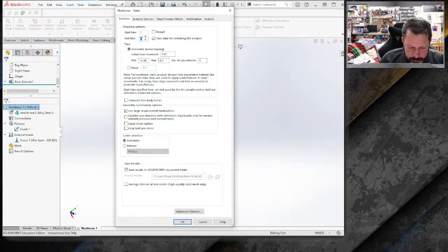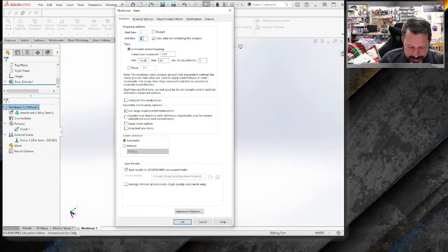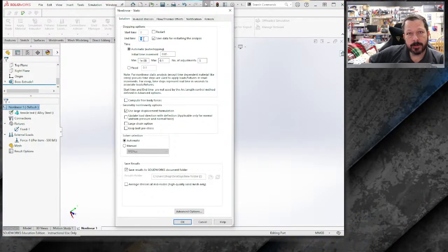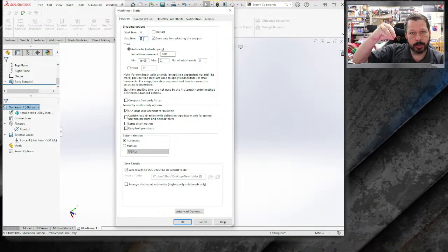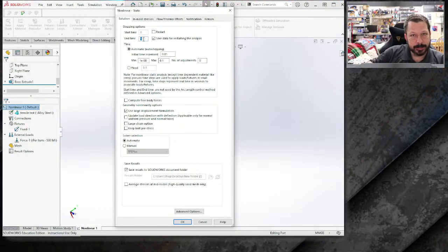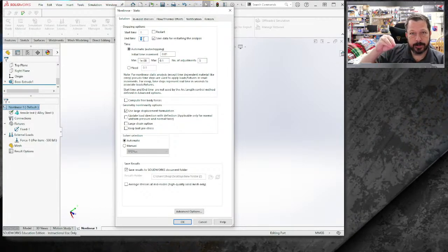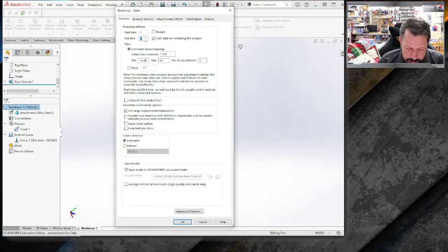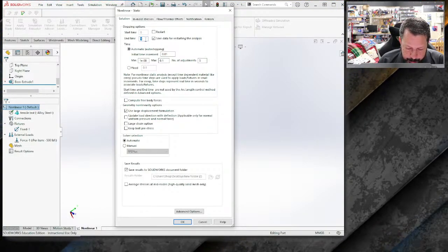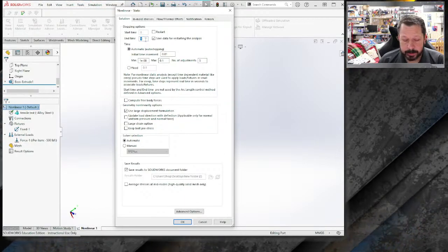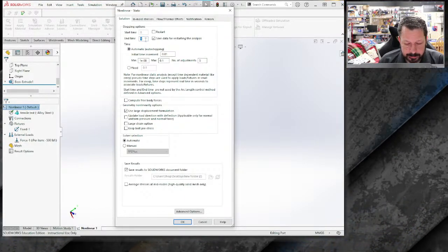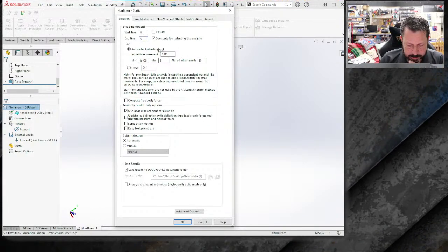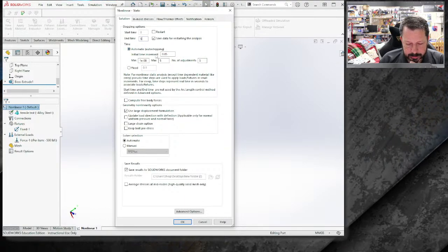So it's set up for 1 second. Now these tests are normally 10 seconds long, maybe, because you're very slowly pulling them apart. You're not really trying to yank them apart. It's a very slow process. So I might want more than 1 second on here. But I also don't want the simulation to run very long. So let's go for 5 seconds. We will let it automatically increment the time.